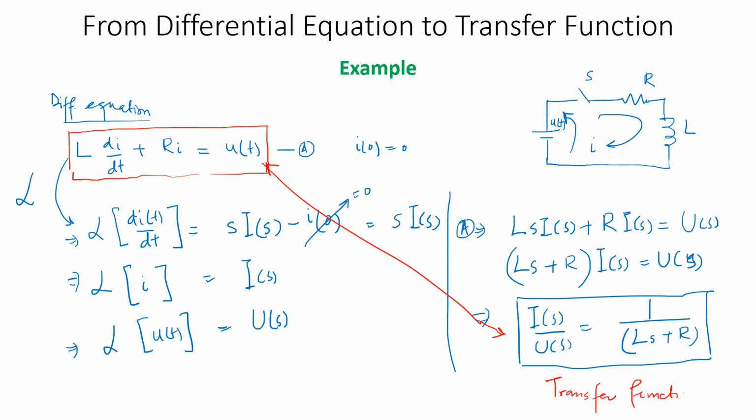And it fulfills that criteria. The transfer function is going to be based on Laplace transformation with zero initial conditions, and it is going to be structured in terms of output over input. So in this case, the output is the current passing through this RL circuitry, and the input is the voltage applied to it by the voltage source. So you're going to conduct similar exercises, and you can very easily do by inspection this conversion from differential equation to Laplace transformation.